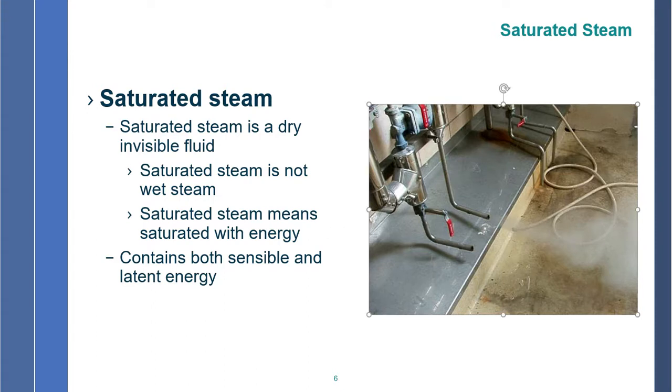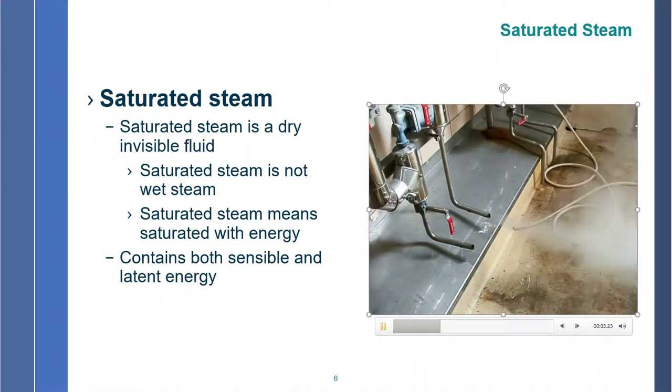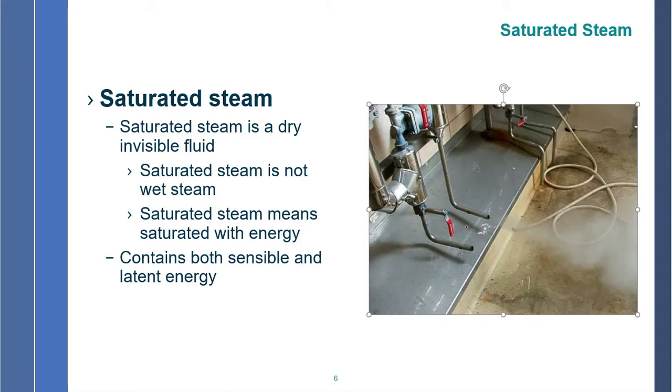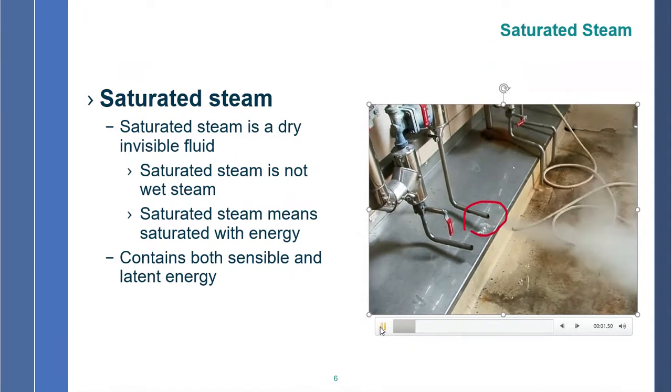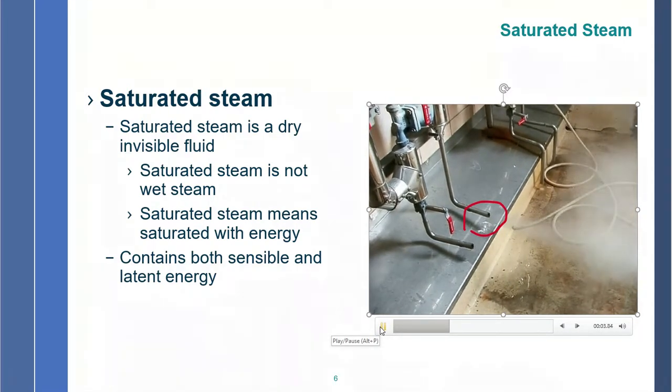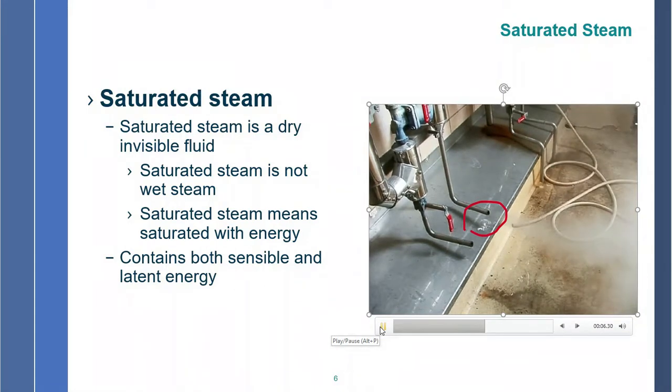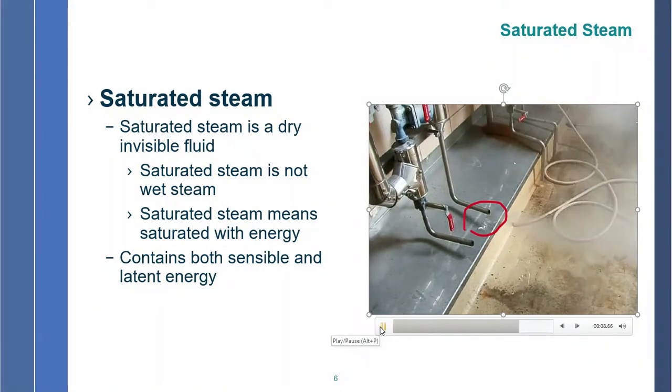So as you can see right here, when the steam is discharging to atmosphere, right here, it's invisible. You really cannot see it. So remember, saturated steam is a dry, invisible gas. You cannot see it. It contains both sensible and latent energy. Saturated with energy, not wet.